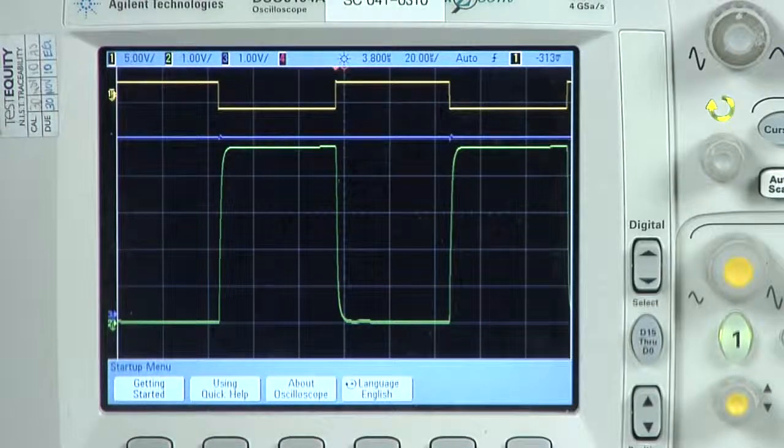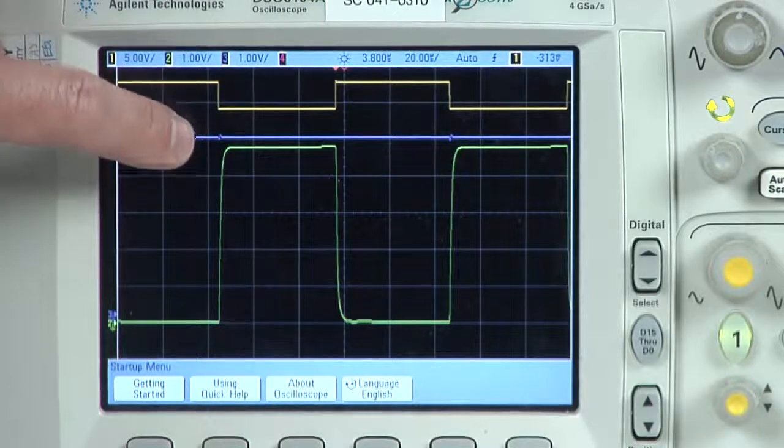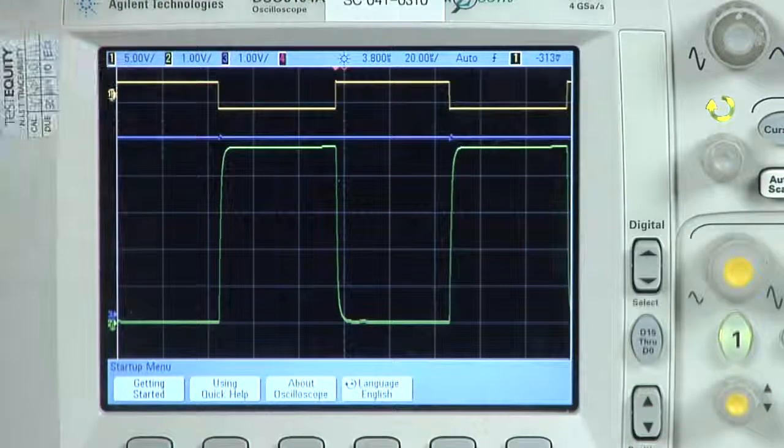Finally, the purple trace shows the voltage at the input of the mux. Remember that I was talking about voltage glitches which can occur from input protection diodes turning on. This is the node where you would see those. You can in fact barely see a very small, very short glitch. This is due to the charge injection from the mux itself, which is a much smaller effect than input rush current through op-amp protection diodes. This glitch very quickly resolves itself so that the op-amp output can settle to the final value without problem.